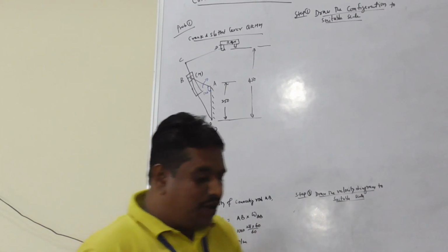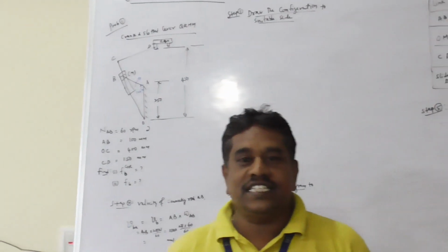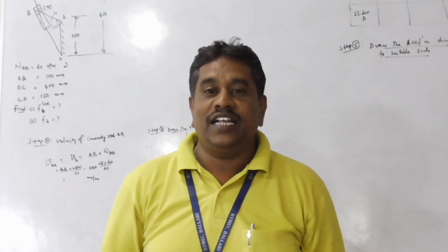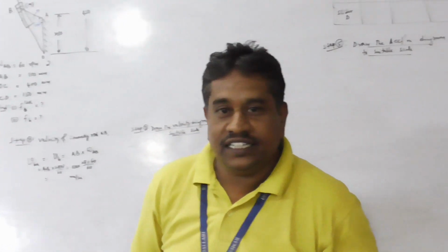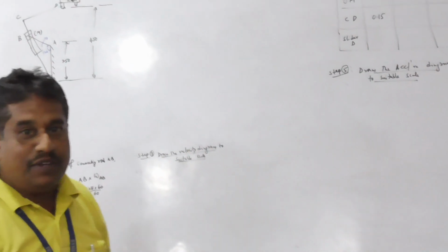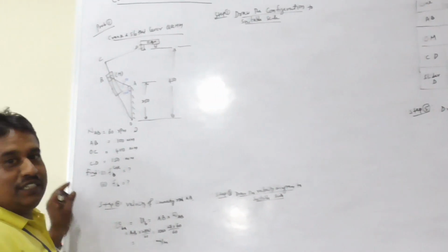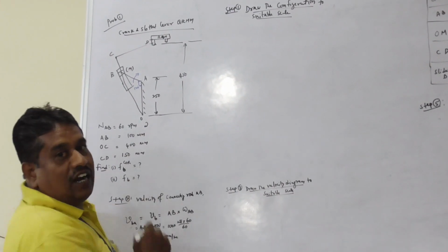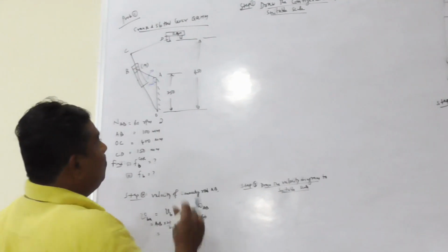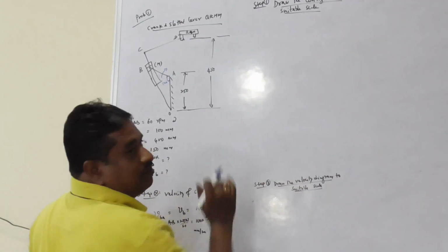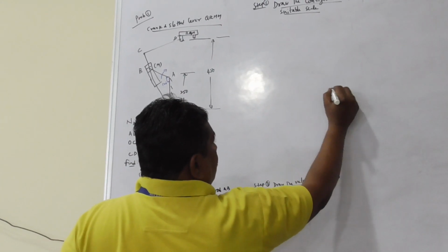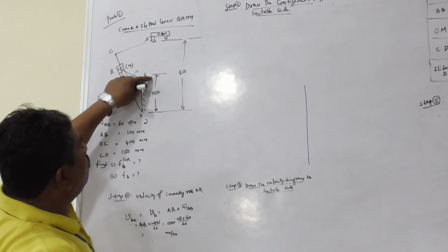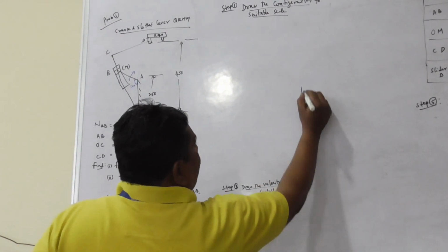As you know, whenever a moving body slides on an oscillating link, the moving body will have an acceleration known as the Coriolis component of acceleration. In a similar way as we solved the previous problems, the very first step is to draw the configuration to a suitable scale. How to construct the crank and slotted lever quick return motion mechanism for the given data? Let us first draw a vertical line, as per the scale of the configuration diagram, equal to 250 mm. OA is 250 mm.